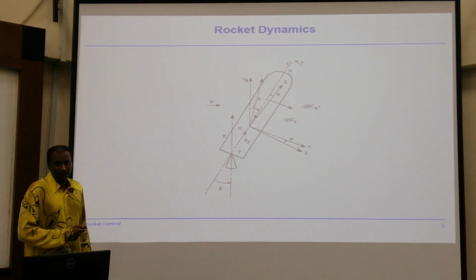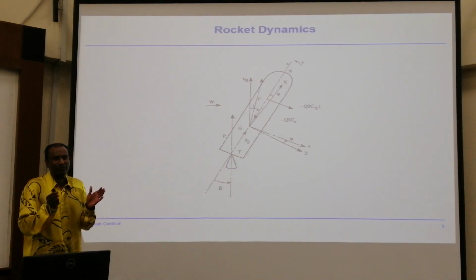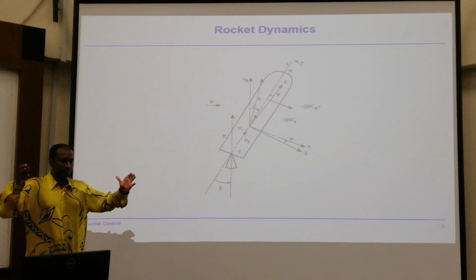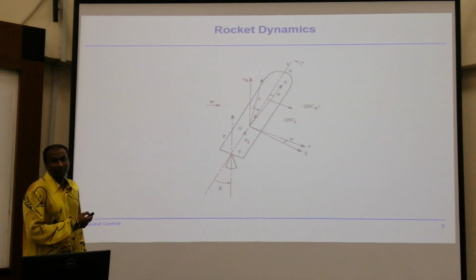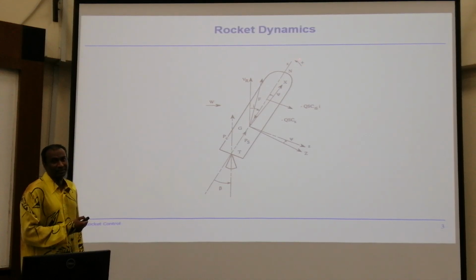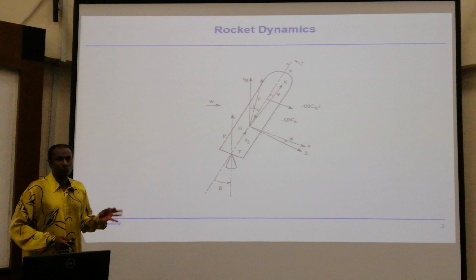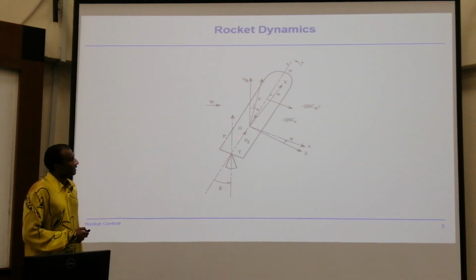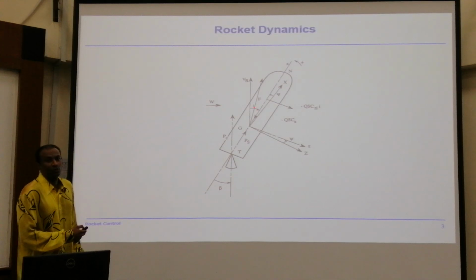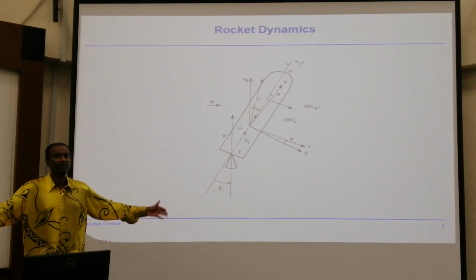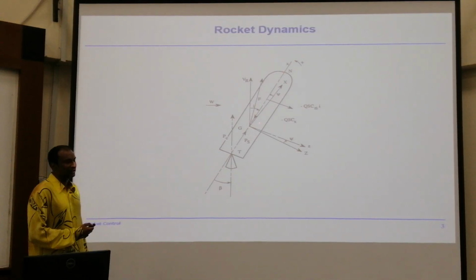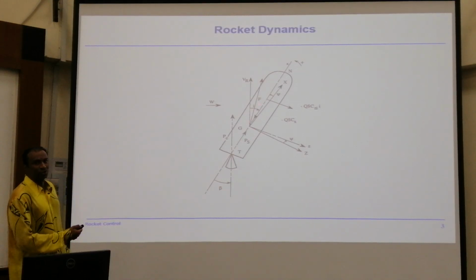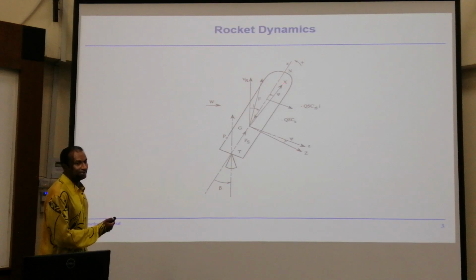Now, in principle, both the center of gravities are quite close actually. Because if you look at rocket engines, normally at this point you have your payload, which is practically your satellite, or maybe any cargo that you want to take into space station. So if you look at the rocket calculation, stage 1, stage 2, stage 3, the biggest bulk is always in the lower stage, because that's where you have your maximum amount of fuel, booster is full, everything is full. So technically speaking, your center of gravity is always much closer down to the nozzle. It will not be up here for sure.